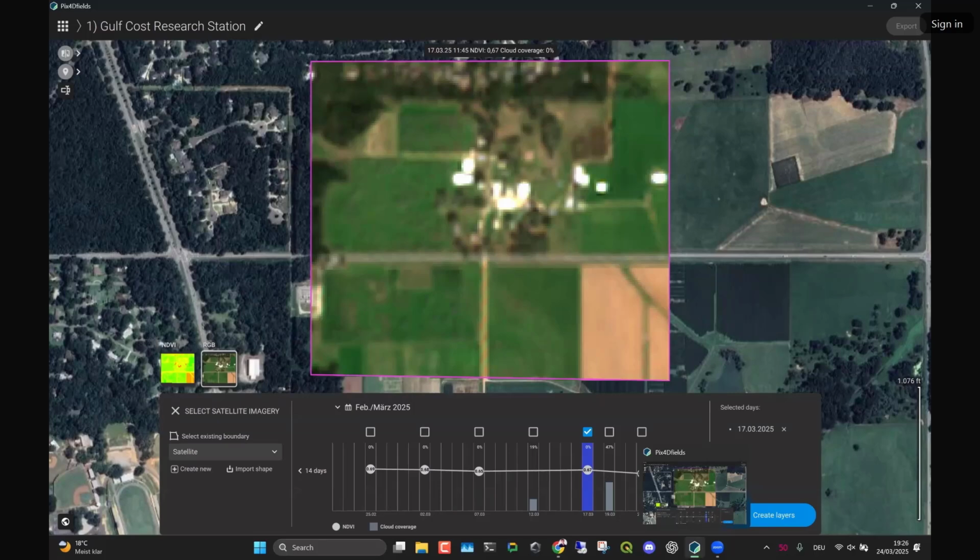Maybe for the audience on Zoom, there was a really important question: should you have de-warping on or off? You should have it off, because otherwise it breaks our photogrammetry, and then all the data can be shifted like 10 feet or so. So make sure to turn it off. You can tell it's off because you have some vignetting effect at the edge of the image, like a little black shadow. That's exactly what we need for good photogrammetry. So turn it off, please. Pix4D processes raw data, not pre-processed data.